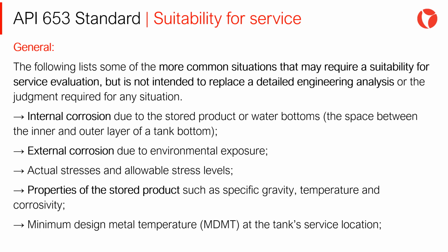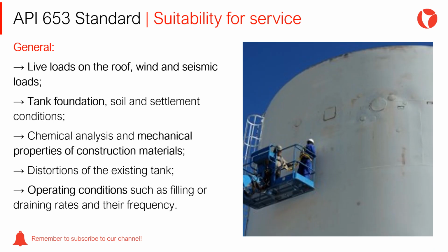The following lists some of the more common situations that may require a suitability for service evaluation, but it is not intended to replace a detailed engineering analysis or the judgment required for any situation. For example: internal corrosion, external corrosion, properties of the stored product, minimum design metal temperature, live loads on the roof, wind and seismic loads, tank foundation, mechanical properties of construction materials, operating conditions, etc.